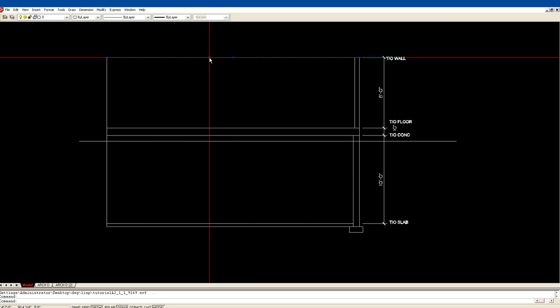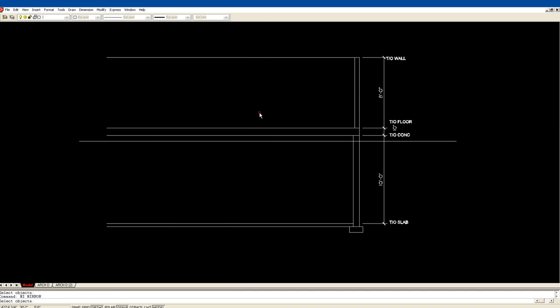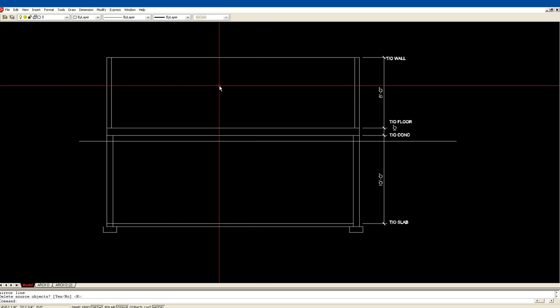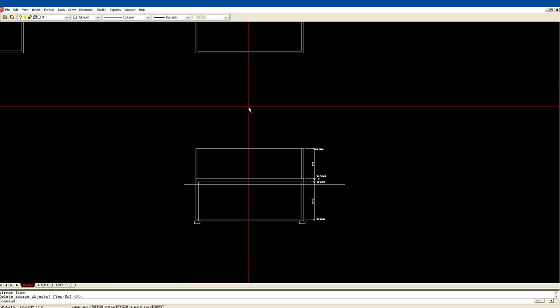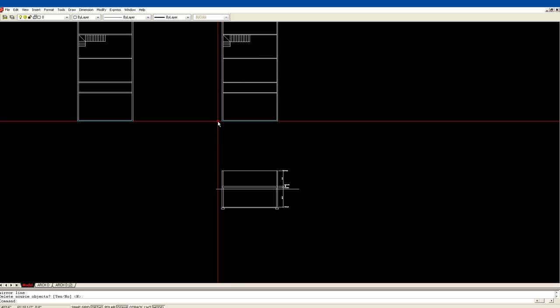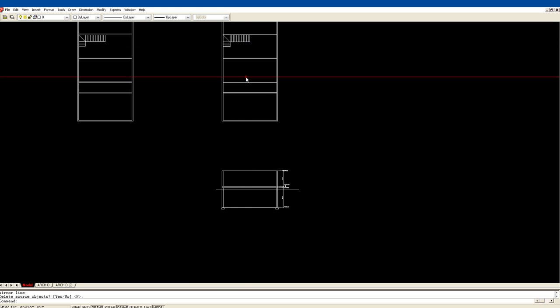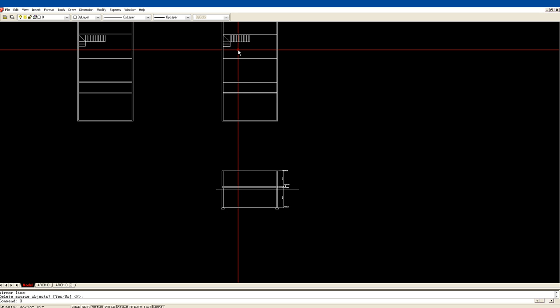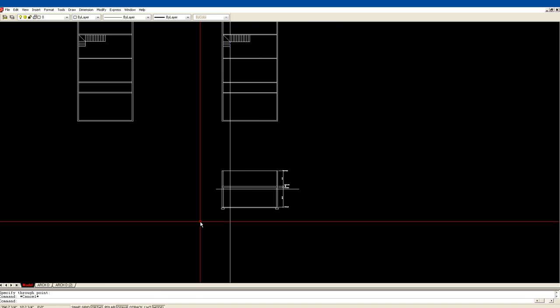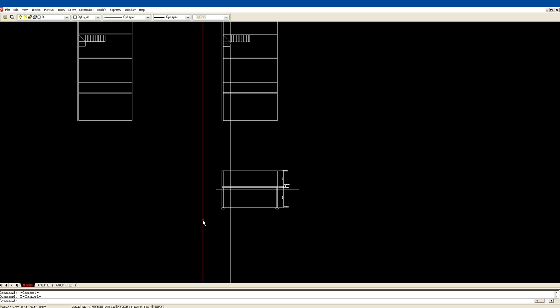Now, this line right here goes from side to side, so I can erase that one, and I can just mirror all of this that we've drawn here. Right in the center there, enter. So really there's the 2 sides of the building. What we've done is a cross section, which looks sort of like an elevation. Here are our stairs, and so we can do an X line vertical just to the edge of those stairs. So that's 30 or 42 inches.